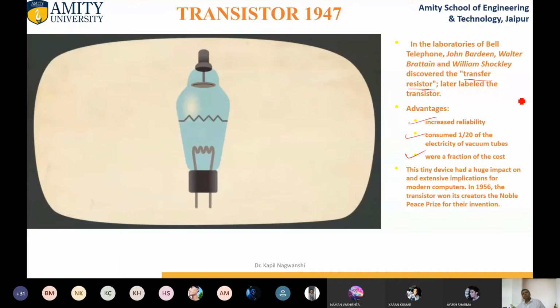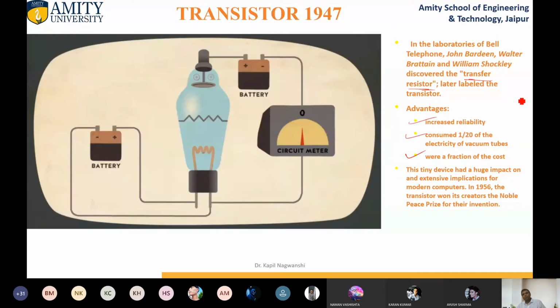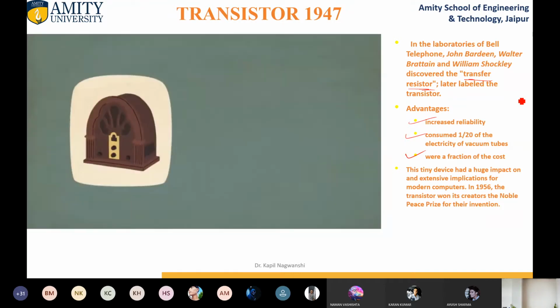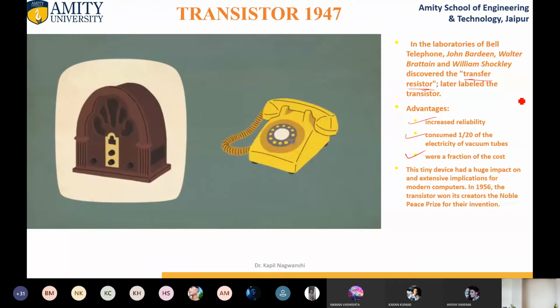This is a wire screen between the cathode and anode through which electrons could pass. Varying its voltage makes it either repel or attract the electrons emitted by the cathode, thus enabling fast current switching. The ability to amplify signals also made the triode crucial for radio and long-distance communication.